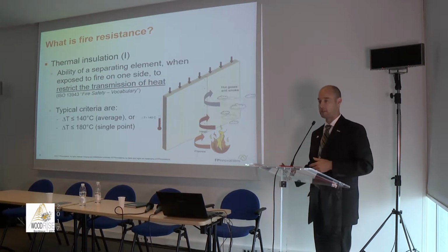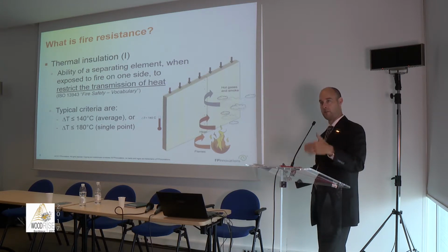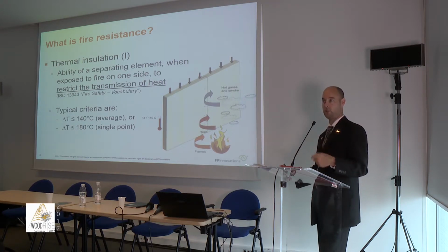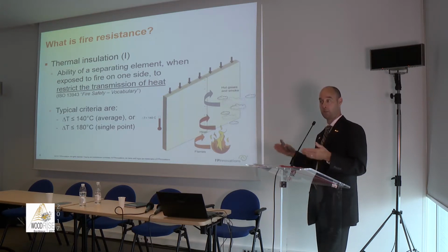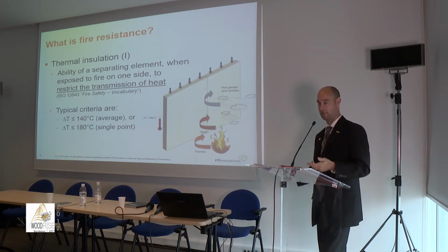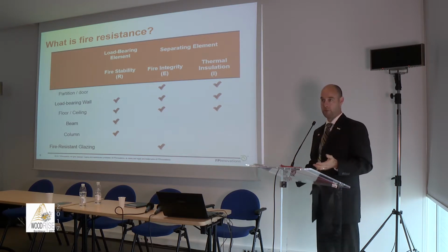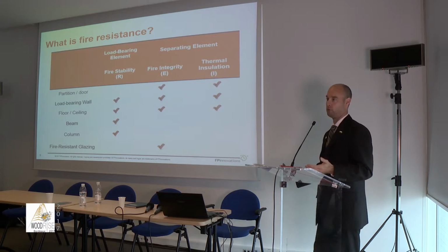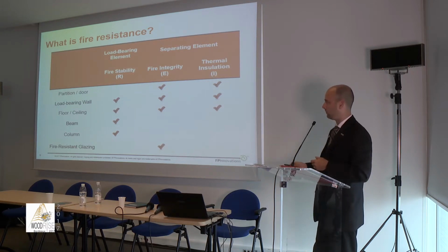And then the last criterion is thermal insulation. You have to limit heat transfer from being too excessive on the other side, so that if you have any easy-to-ignite combustible material, it would not ignite, and you're not allowing a fire to spread from one side to the other, even without flames actually going through the assembly. So not all materials need to fulfill the same criteria. Obviously, a column or a beam cannot limit a fire from spreading from a compartment, so it only has to fulfill the load-bearing criterion. And these are well defined in all the standard test methods anyway.